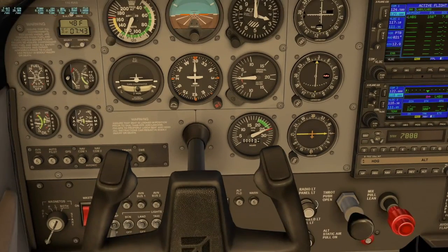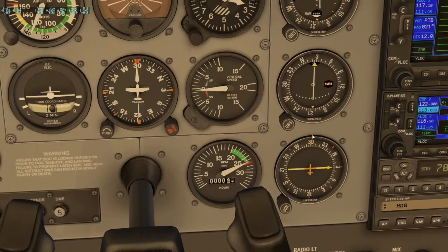Back again to our cheat sheet. At 60 degrees I have to go this direction, just like I have to go abeam to it. What is this direction? It's 210. So when I hit this radial, the north, the 000 radial, I have to turn left to direction 210.